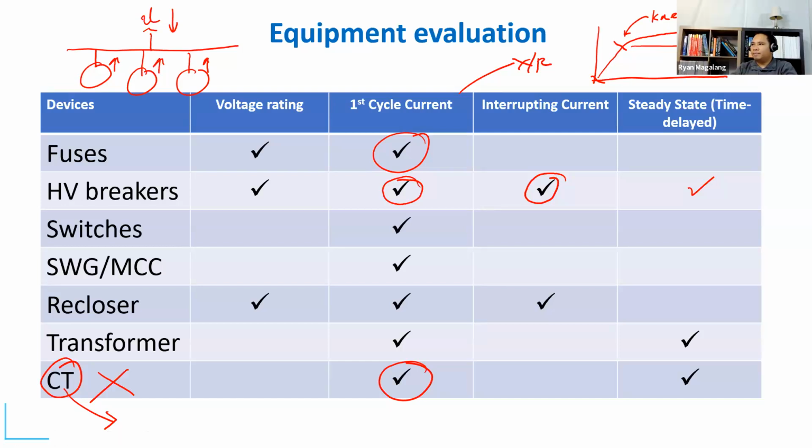Yeah, in general, yes. Normally sa mga facility naman, o sa mga industrial installation, there's a combination of things there. So normally you'll find fuses, breakers, and relays all together as a facility. So for example, ang smaller motors, you'll find a combination ng breaker and starter. And then yung medyo malaki ng kaunti, may fuse and may breaker pa siya.